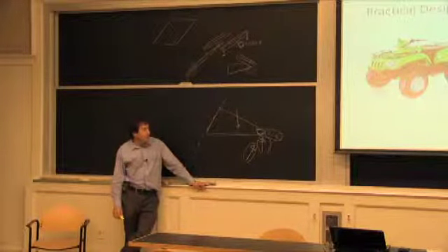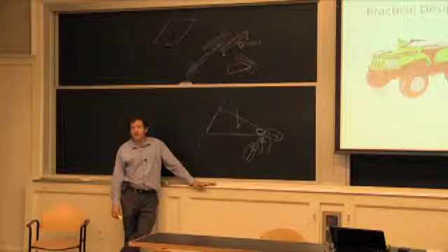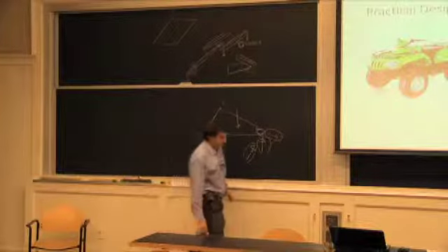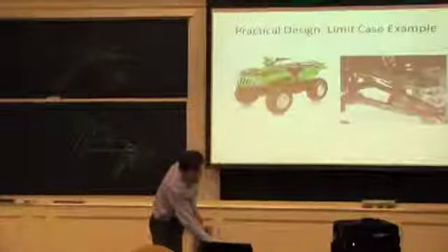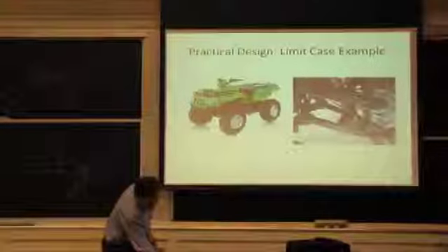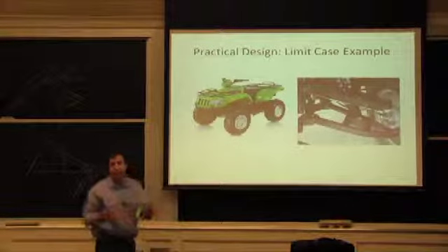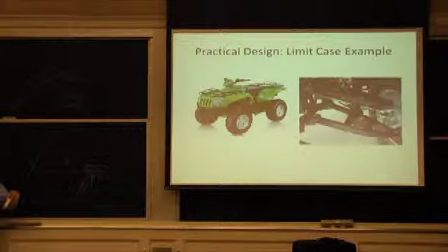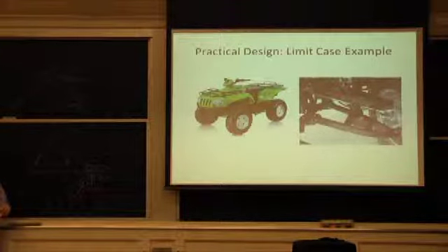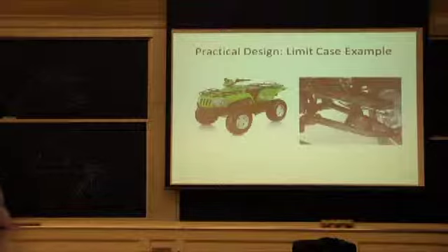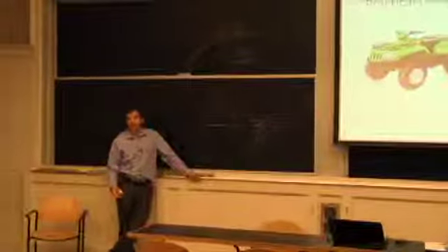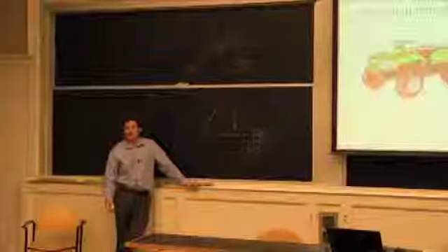And that's why they do a lot of field testing. So they hire people to go out and they put force transducers. They are mounted right between the hub and the wheel itself to capture all the vertical, torsional, and shear type of forces between the hub and the wheel for different driving conditions.